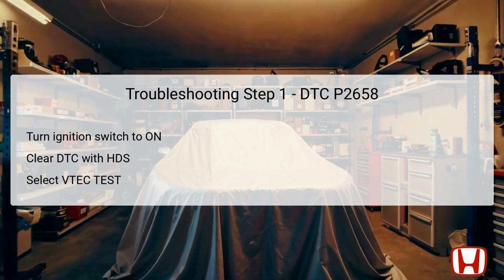The initial troubleshooting step for resolving DTC P2658 involves turning the ignition switch to the on position, which allows the vehicle's electrical systems to activate without starting the engine. After doing this, it is essential to clear the existing diagnostic trouble codes, DTCs, using the Honda Diagnostic System, HDS. The HDS is a comprehensive diagnostic tool that interfaces with the vehicle's onboard computer systems.